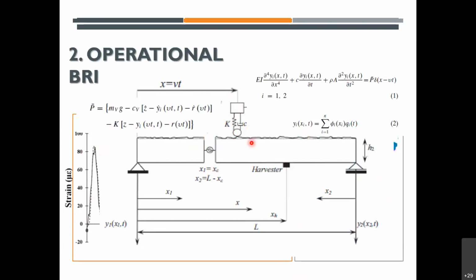And then you can always think of the load, which can be just the mass times its acceleration due to gravity, the weight, but then also the coupling because of the degree of freedom between the vehicular degree of freedom and the bridge degree of freedom and the surface roughness. So you see the vehicle goes past, and because of the Dirac delta function, it keeps on sampling whatever is in the spatial domain into the time domain. And here again, it's the coupling, which essentially renders the stiffness and the damping matrix time dependent.